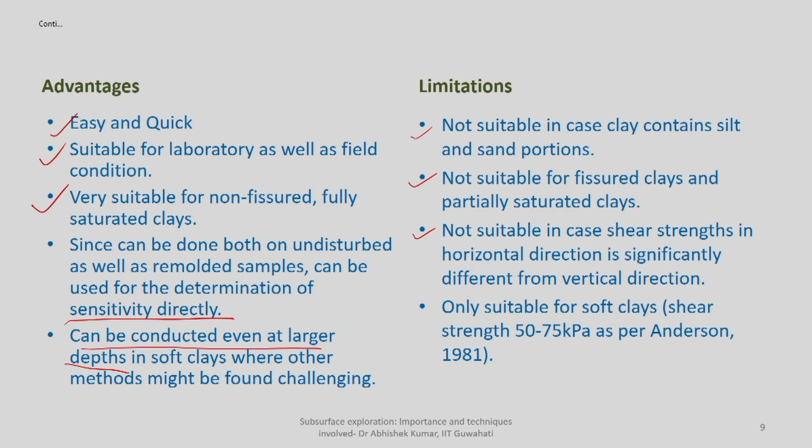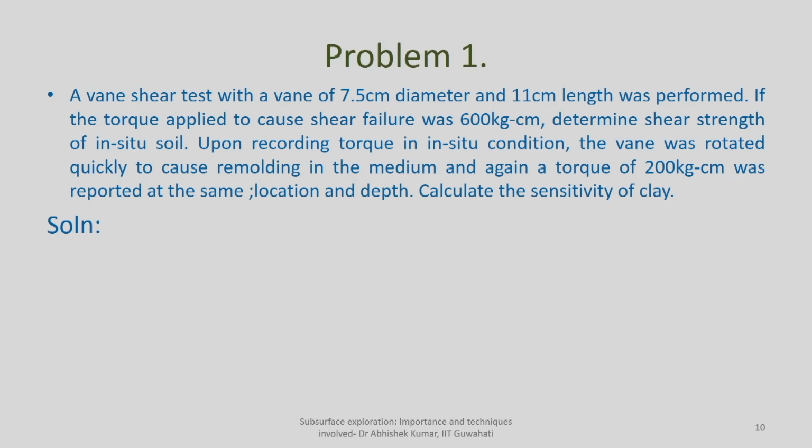And the third and the last point is, it can only be used for very soft clays. So the shear strength ranges from 50 to 75 kPa as per Anderson 1981. So it cannot be used for very stiff clays or other materials, particularly partially saturated ones. So with this background about vane shear test, today we will be discussing